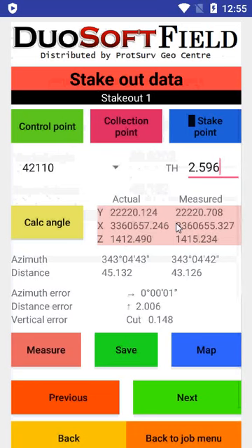Okay, so from this I can tell that, with regards to angles, I'm fine. I'm within a second in angle, but I need to move further by 2 meters and go down by around, say, 14 centimeters.